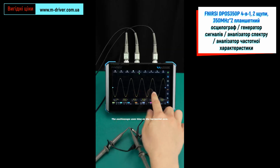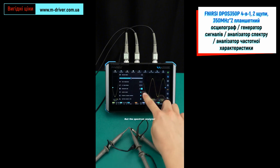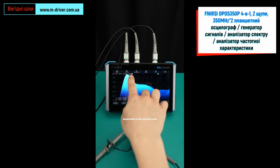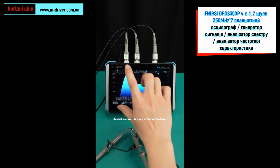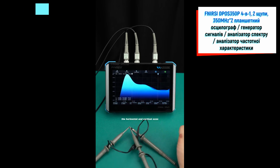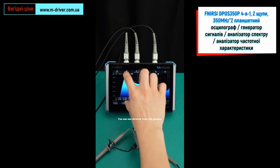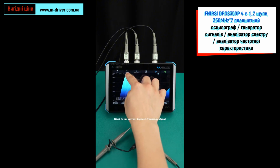The oscilloscope uses time as the horizontal axis, and level as the vertical axis. But the spectrum analyzer, this is the graph obtained by the oscilloscope after Fourier transform, is based on frequency. Amplitude is the vertical axis, and decibel microvolt is the unit of the vertical axis. By combining the horizontal and vertical axes, you can see directly from this graphic what the current highest frequency signal is.